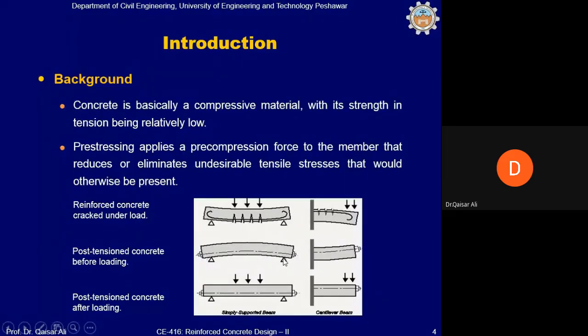We press this by some mechanism, and if we are able to press this beam up to an extent where, when the load is kept on the beam and the tensile stresses are produced, whatever compression has been produced before the beam is subjected to loading will be cancelled.